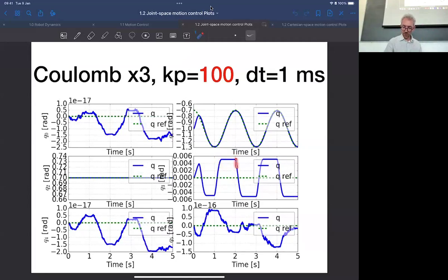And this is the moment where the torque generated by the motor is able to overcome the Coulomb friction. And so the joint can move again towards the target, but then it overshoots, and then it sticks again, and then it moves towards the target, then it overshoots. And so you have this kind of square wave behavior. That's very typical of Coulomb friction.